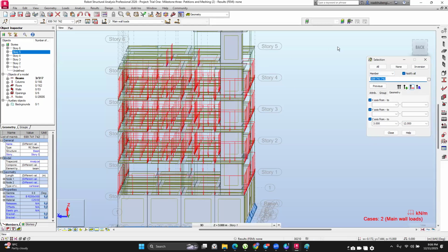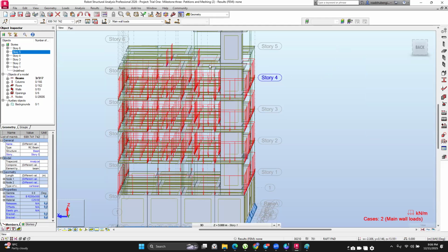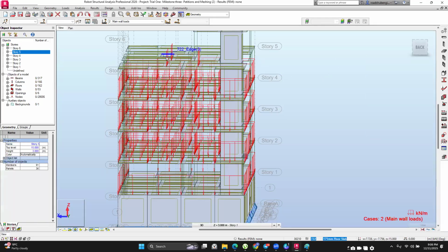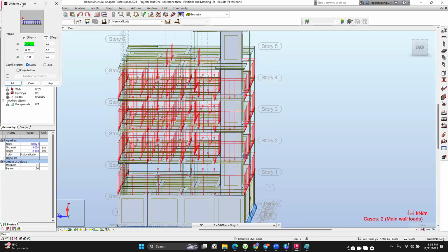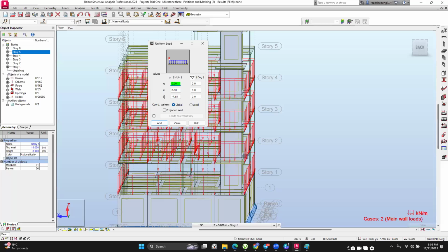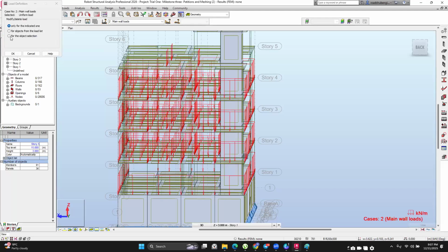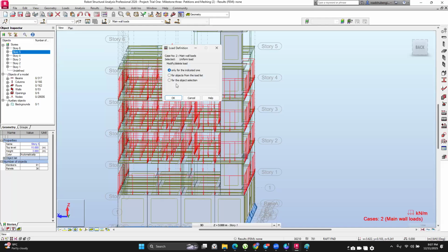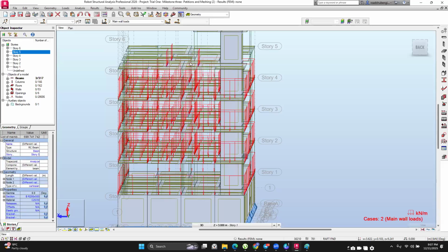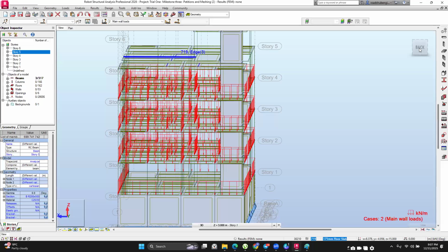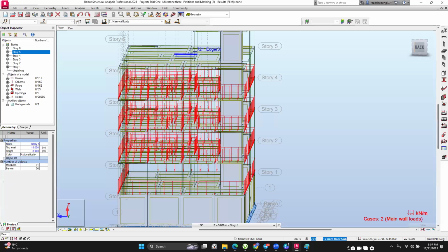Then once you do that, you can press escape and then click twice on this load in quick succession. And then change it to 0 first. You can see the load is there, negative 7.65. We had calculated it earlier on. So have it as 0, then click on add. And then we go with option number 3. It allows us to enter the list. So paste the list and then apply. And then those loads are deleted. So we are together up to there.